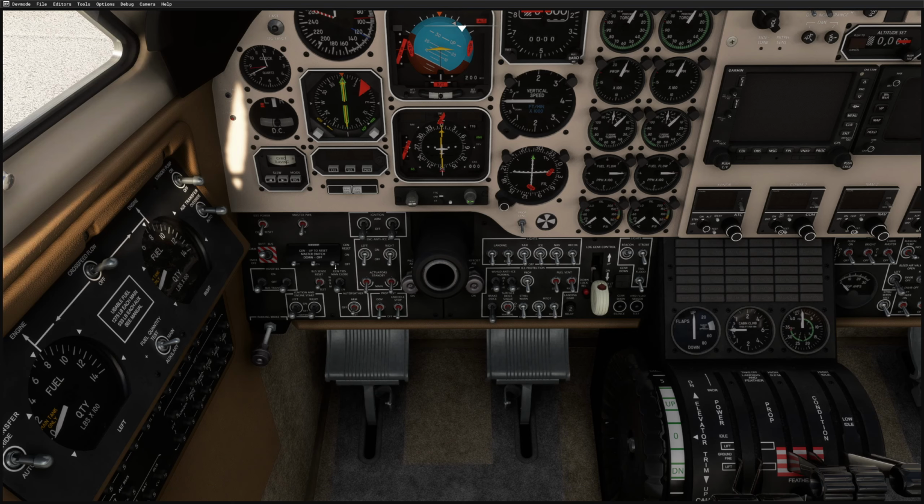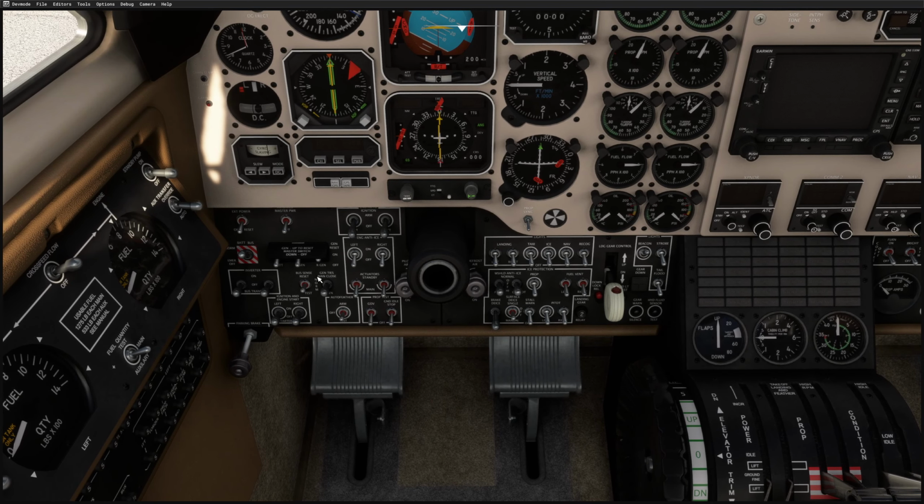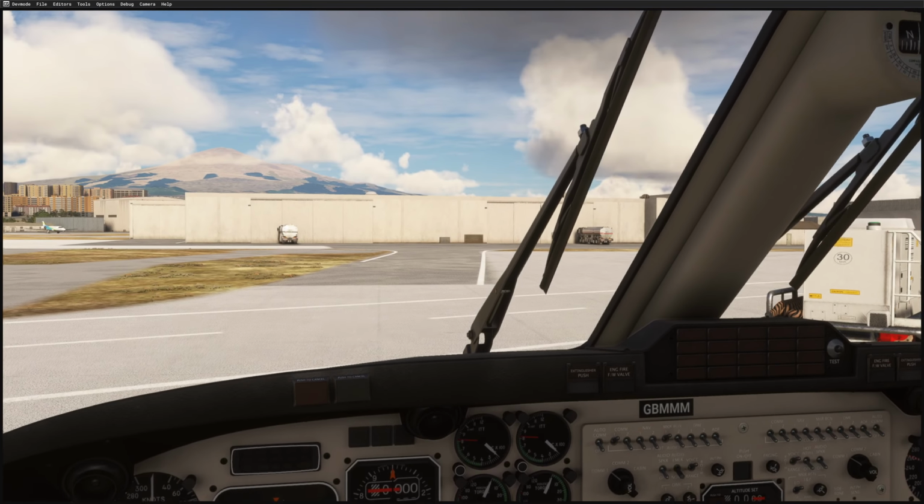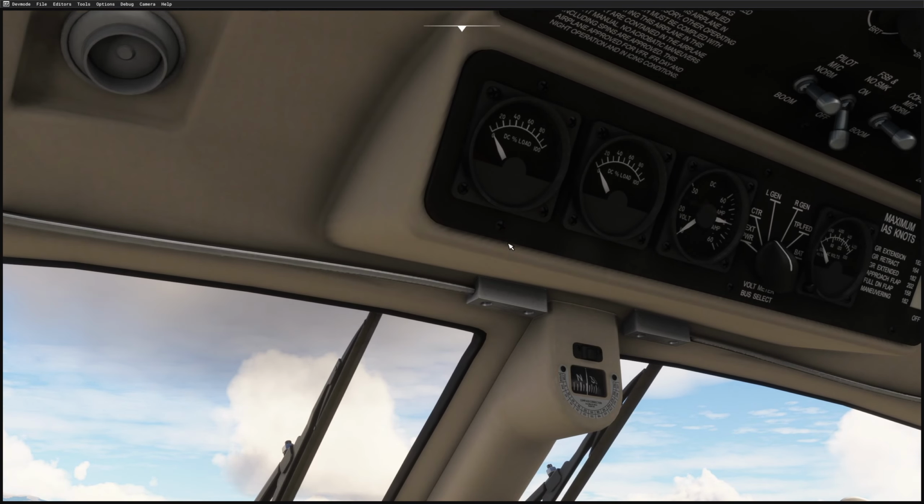It's to do with the generators. They've got an off, an on, and the reset at the top. Normally the reset is spring loaded, so as you move it up, it just clicks, does the reset, and then lets go. But we need to hold it in the up position when we check the voltages and make sure the generators are working properly using the gauge up here.